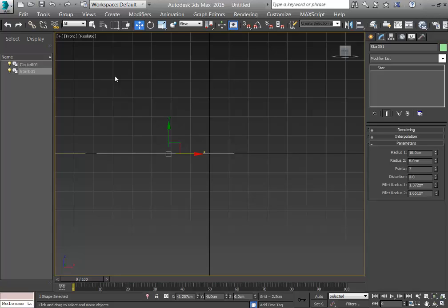Actually, I want to draw the line starting from ground to up. And if you want to draw a line from ground to up, you need to see the z-axis. And you can see the z-axis either from front, left, right, or back. So you can use front, left, right, and back. But you cannot use top and bottom, because from the top and bottom, you will see the z-axis as a single point. That's why you should change your axis, either front, left, right, or back. Here I prefer the front one, no matter what you prefer as well.